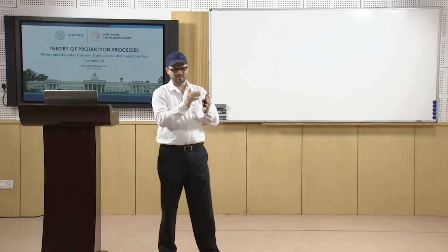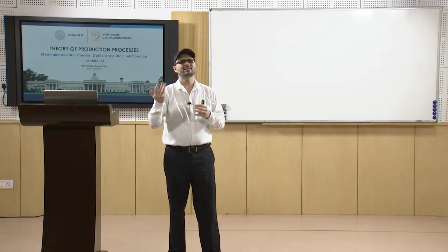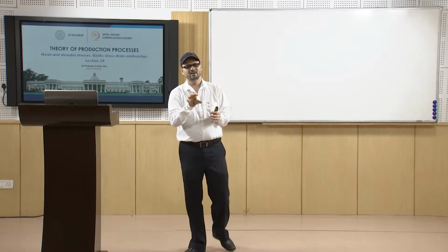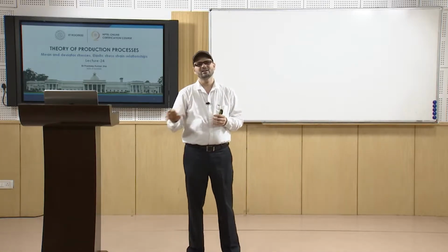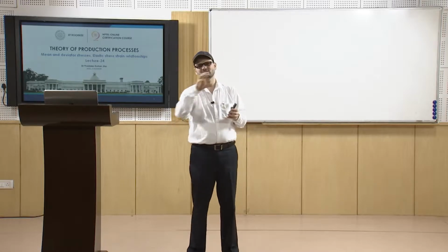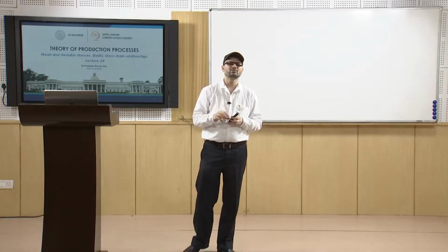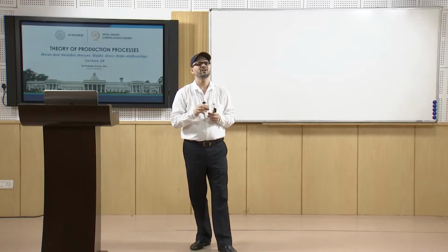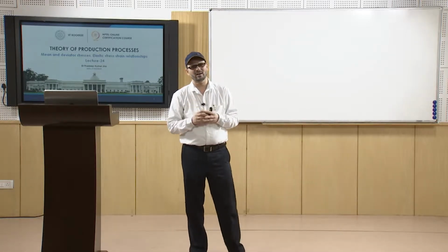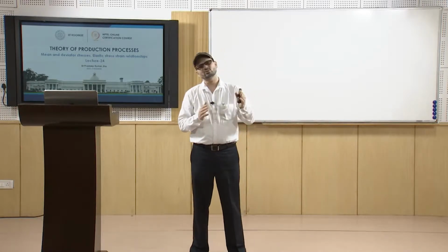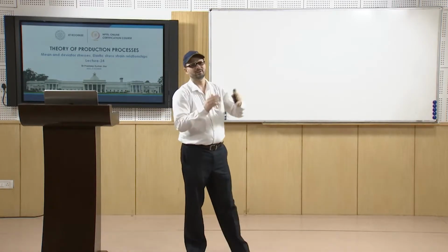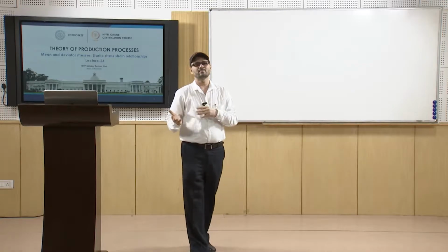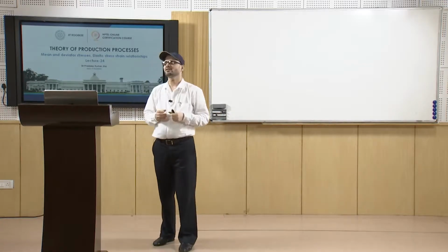So once you have sigma xx, sigma xy, sigma xz, where sigma xy you can write as tau xy, and similarly sigma yx, sigma yy, sigma yz, sigma zx, sigma zy, sigma zz, from the diagonal part you remove the mean part, sigma mean. Sigma mean is sigma x plus sigma y plus sigma z by 3. That way you will have two matrices, one with the mean component and another with the deviator component.